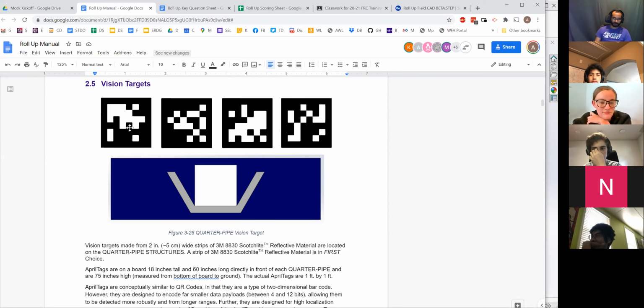The other thing that April tags allow you to do is relatively easily get your angle from how they're posted. So if this is like flat against here, you can know that you're looking at it at like a 45-degree angle or at a 30-degree angle. So you can know how far off of center you are to the April tag. So the algorithms that use this are pretty cool. There's actually a phone app, if I can figure out if I still have the correct one on here.